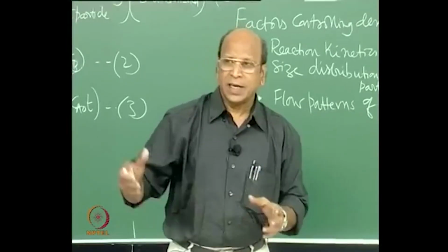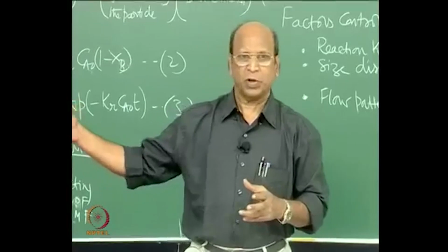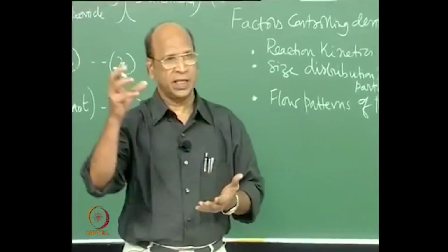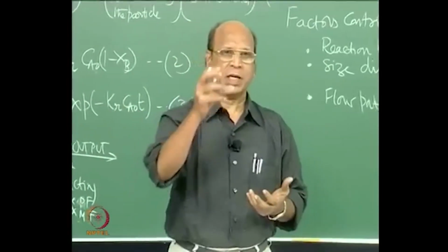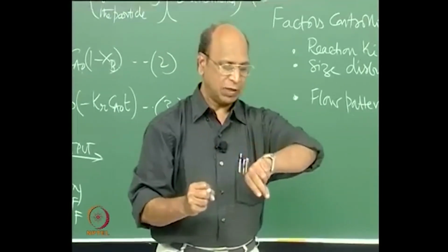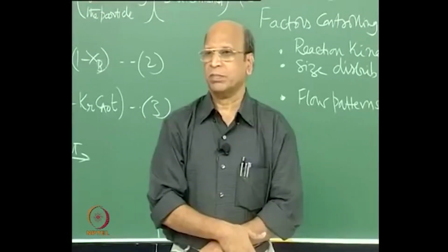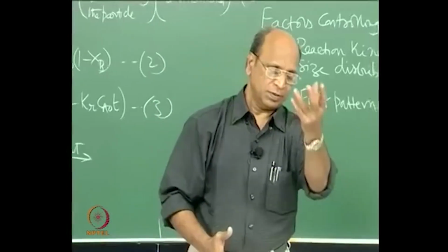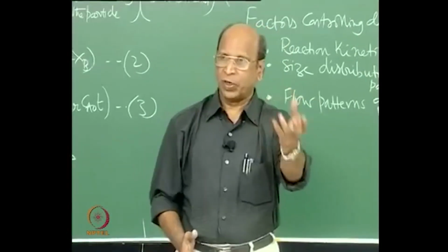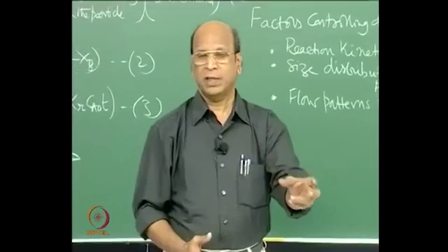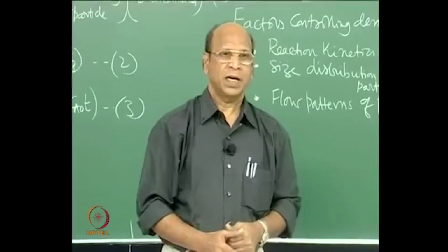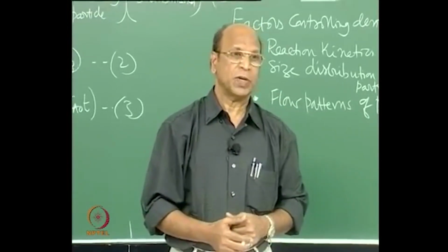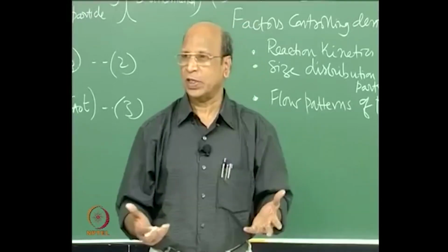Design is not that difficult when we have that; you have to take the average. What is the conversion in the 1 centimeter particle, the conversion in the 5 mm particle, and the conversion in the 1 mm particle? You just have to average it out, a weighted average. In fact, 20% may be your 1 centimeter particles, maybe another 40% may be your 5 mm particles, and another 40% may be 1 mm particles. So that is not difficult for you, you can easily handle it.